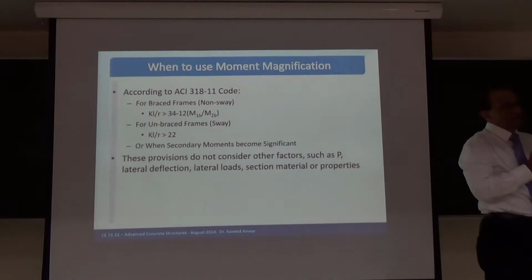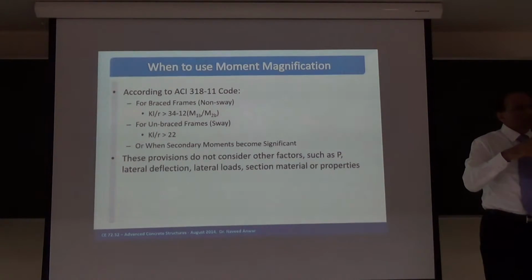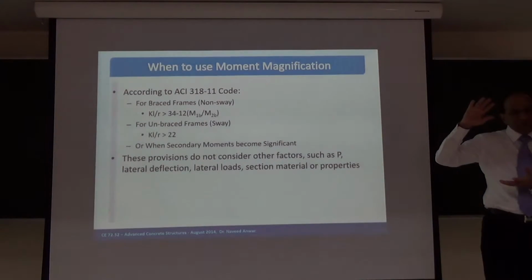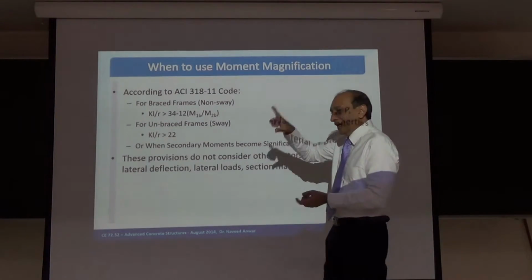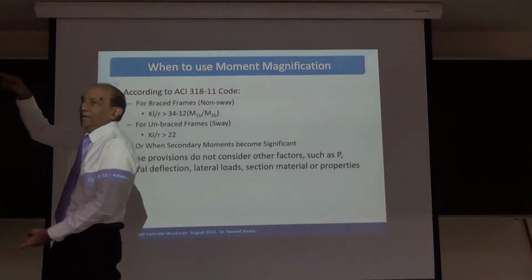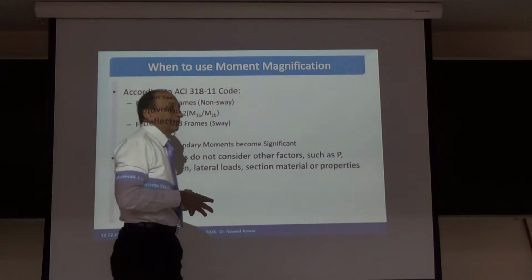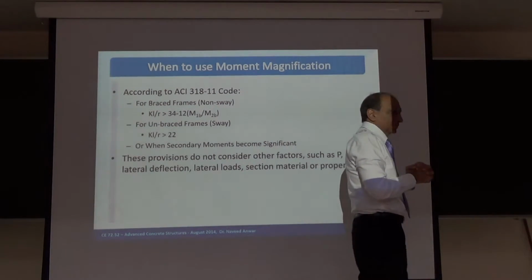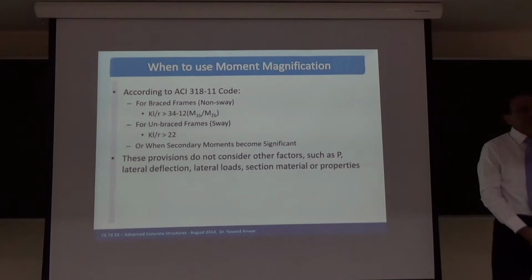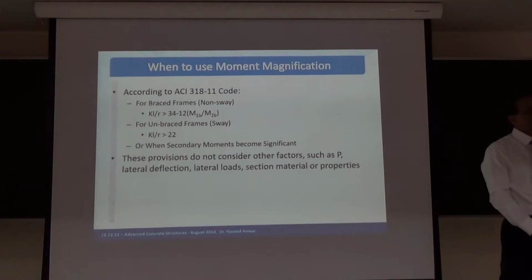For small buildings, especially on the ground floor, the height tends to be high because sometimes the foundation is below, there are missing ground beams, and for the ground floor, they tend to make higher floors for mezzanines and so on. So for short buildings, the problem actually gets very, very severe. And if we miss that, then we are in danger of the column failing first.